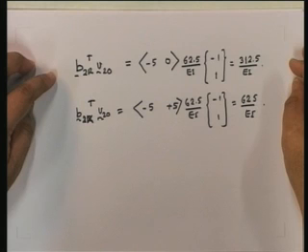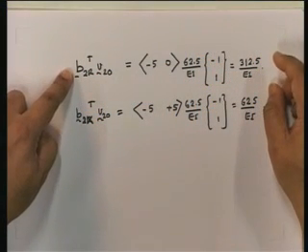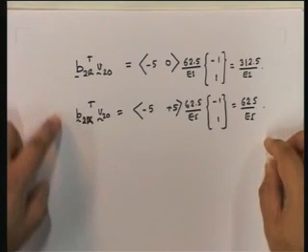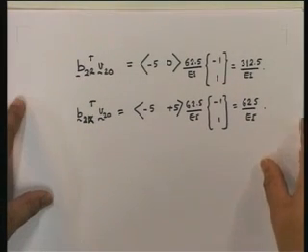I do not have the terms for SI0 over here because in this particular problem we've already seen that SI0 is 0, and therefore I'm just dropping those terms out. So now all I need to do is evaluate all these terms and then put them into the equation. The first step is to find out the summations. Note that since Vi0 is equal to 0 excepting for I equal to 2, the summation term only has these 2 terms, and I found them out. B2R transpose V20 is 312 upon EI, and B2X V20 is 625.